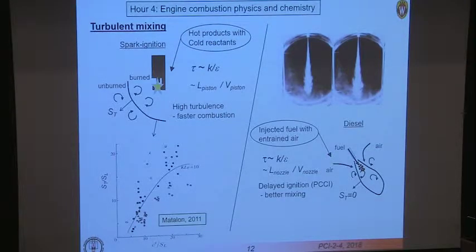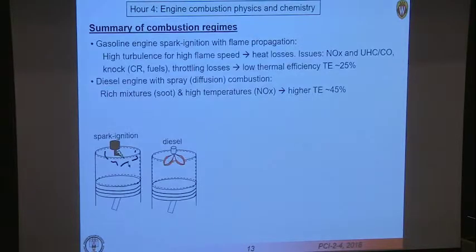For diesel, here are our diesel jets. We inject the fuel. Because of its high momentum in the form of spray droplets, they exchange momentum with the air, entraining the air into the combustion region. Here we set up a diffusion flame. The characteristic mixing time is again associated with the nozzle parameters, the injection nozzle diameter and the injection velocity. So that's very important when we talk about engine combustion, to consider turbulence.